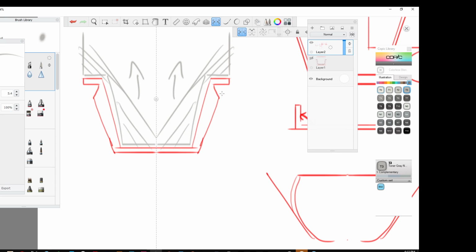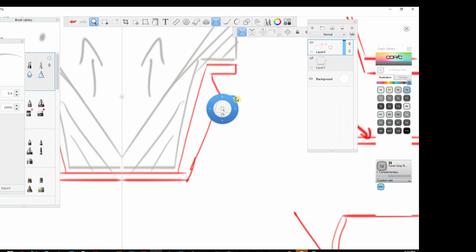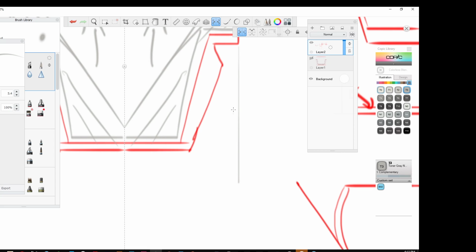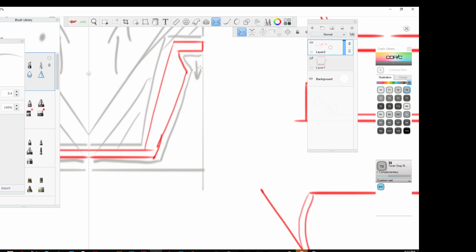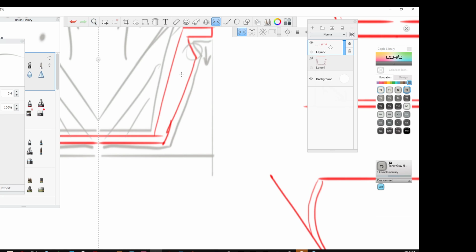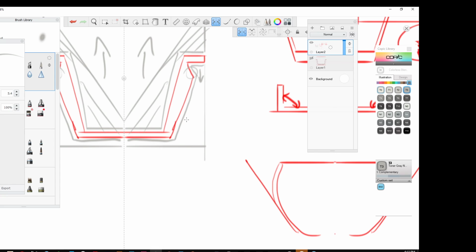Now what happens is, here you've got an undercut. And what that means is I can't simply make this tool. And the reason for that is if I pull it down this way, it gets hung up here. Sometimes, depending on the part, depending on how much of an undercut it is, and this is where you always talk with your manufacturer, because all manufacturers are different. One may say, yeah, we can do it. Another may say, that's not what we recommend. If you do that, we're not going to guarantee you the parts are nice. But for some parts, if it's really flexible, you could pull it off like that, or you could increase how much force is used to push it out.